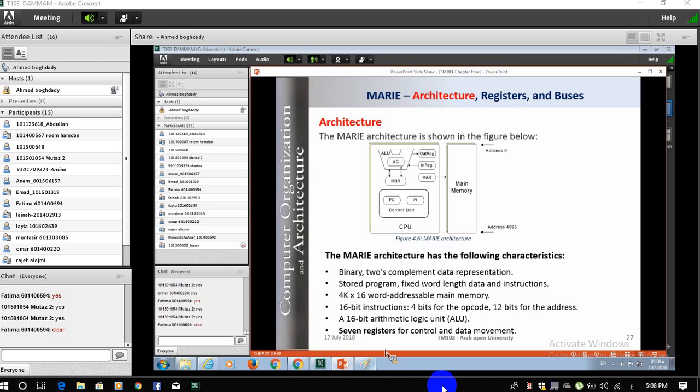So how can I read specific data from the CPU if I have these registers? First step, we check what's the program counter value. It's 6. So we go to the computer main memory where the instruction set is located. We copy its address to the memory address register. Now the program counter value will be 7. Now we copy the data at that address, which is loaded inside the MAR, to the MBR, from the main memory to the memory buffer register.